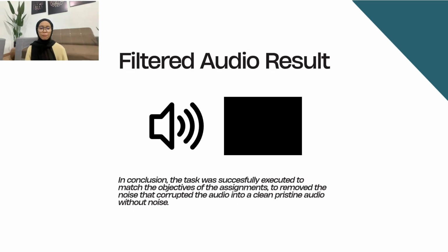Based on both the time domain and frequency domain results, the filtered audio is much cleaner than the original recording. The background noise has been reduced, the 800 Hz interference has been eliminated, and the speech remains clear and understandable.